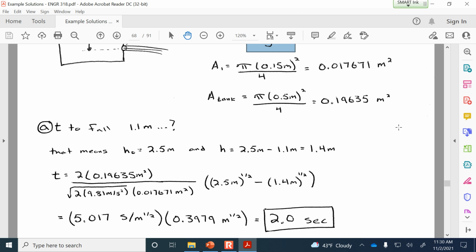Let me ask you this. What about the discharge coefficients that we know in reality the outflow velocity is affected by energy loss? Do you recall how discharge coefficients work with the orifice equation?